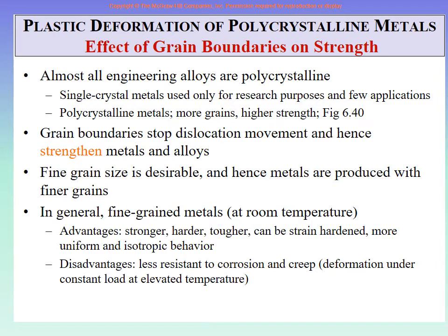This is very simple. So, if there are many grains, then we will say that the material has a fine grain size. We understand, right? That if there is sugar, if there is salt, when it is very fine, the particles of the sugar are very small. If it is coarse, C-O-A-R-S-E, then it is not fine grain, it is large grain sugar. So here also, if there are many crystals, each crystal is a small size, then we say it is fine grain size. Now we say fine grain size is desirable.